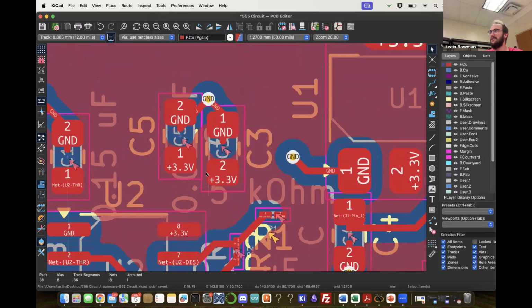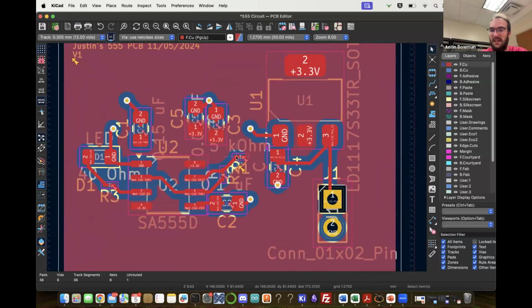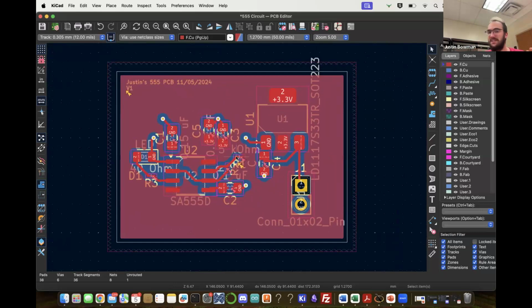And of course, updating the footprints, you now need to update the traces. That's what I had to do as well. I changed the component, but now the trace is all off. Something kind of useful if you find that you've changed everything about your design: bottom right here, there's a selection filter. You can just select tracks, and if everything's messed up, you can just get rid of all of them.